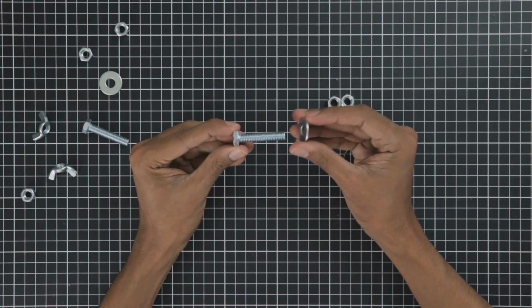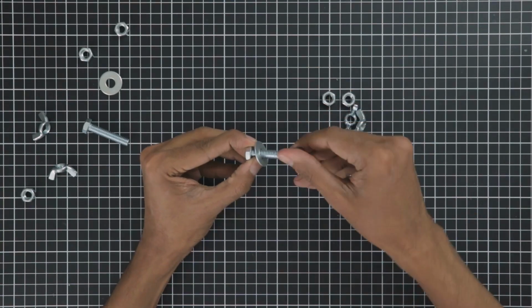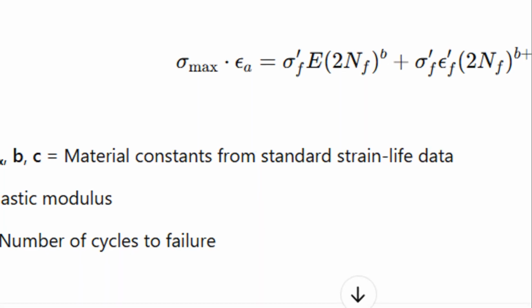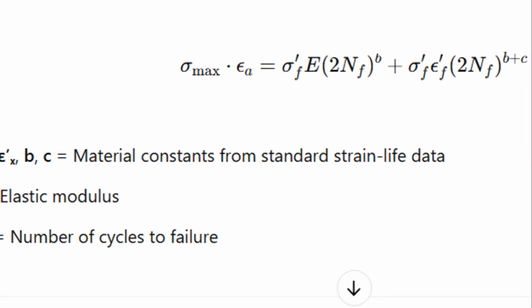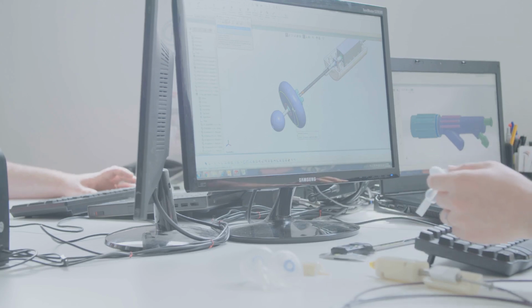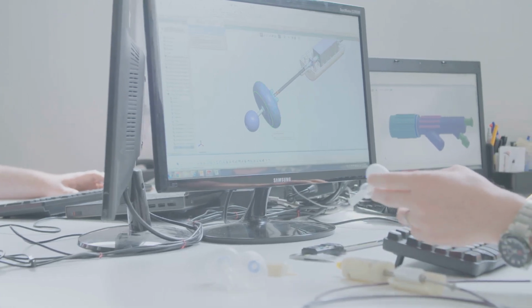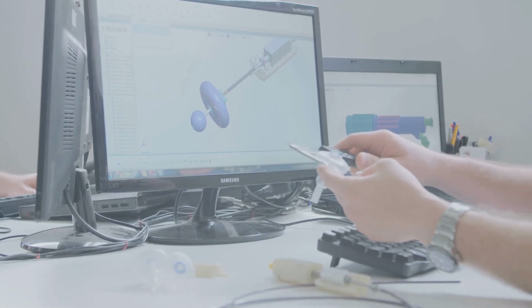They often have a steady or mean tensile or compressive stress upon which the cyclic load is superimposed. A tensile mean stress, for instance, generally makes fatigue life shorter. It's like pulling a rope taut before you start wiggling it. It's more likely to snap. Clever engineers have developed mean stress correction models, such as the Morrow or Smith-Watson-Topper SWT methods. These adjust the baseline epsilon n curve to account for these mean stress effects, leading to much more realistic life predictions for components under real-world service conditions.